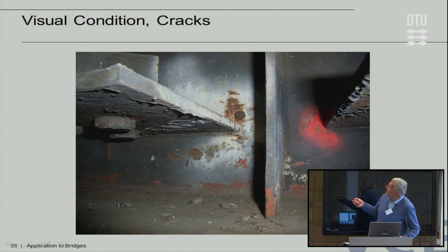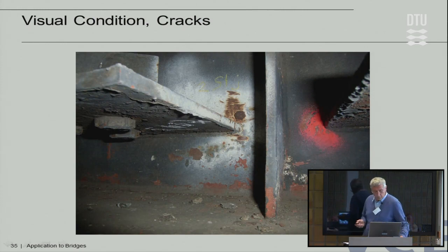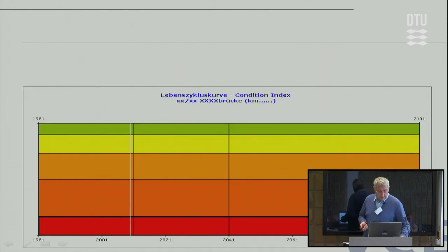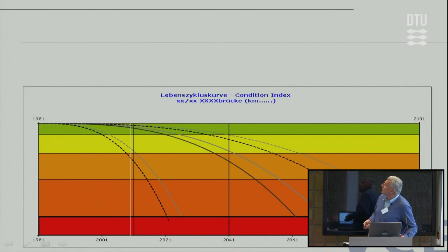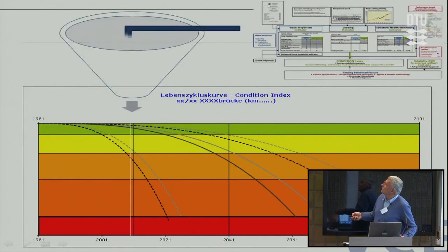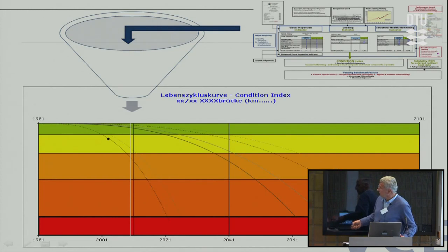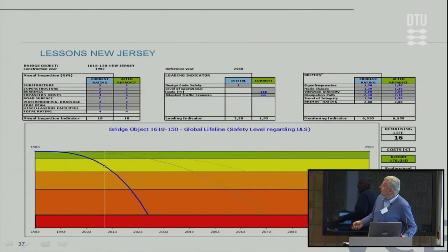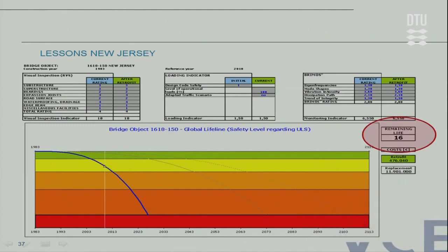Not only were the bearings stuck, there are more than 100 fatigue cracks, very professionally fixed. We did a nice study there on this life cycle. We put all the curves, we put all the methodologies, not the subject in here, but then predict life. And if you look at this information, the main thing to know is how many years of life that bridge has.